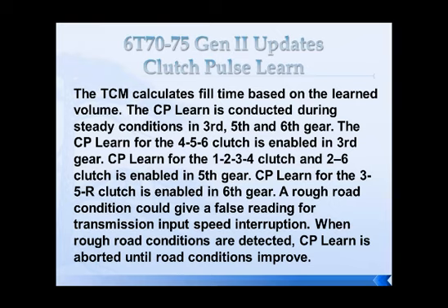So again, there's nothing on the scan tool to show you that this is happening. There's nothing to tell the customer this is happening. It just happens. You feel this little bump every once in a while on a shift, and you're already thoroughly into gear and you feel almost like a tie-up on the vehicle. That's considered normal on these transmissions, and that's part of eliminating the pressure switches on this Gen 2 design.